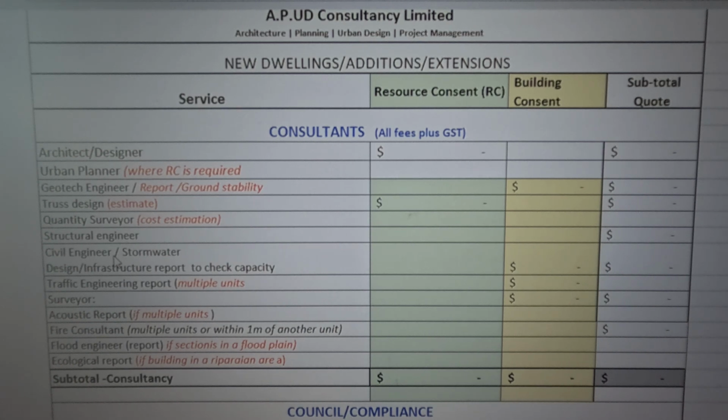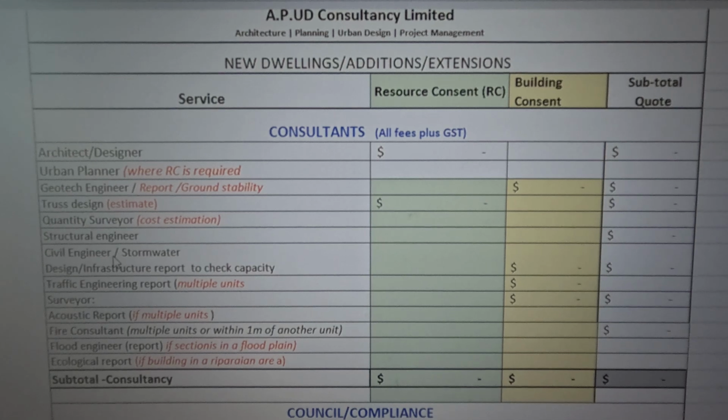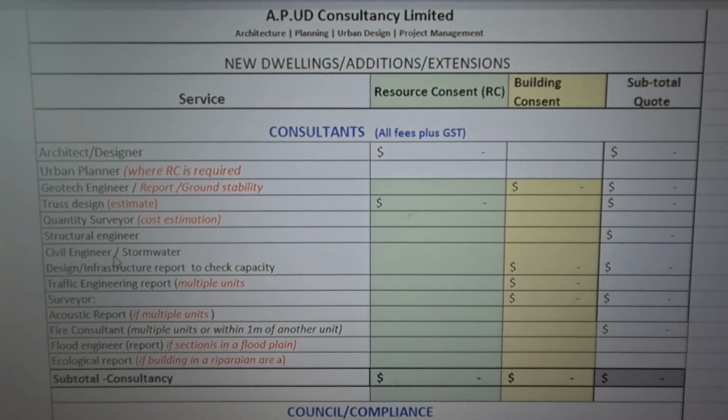Then, of course, surveyor. I've talked briefly about a surveyor. You're going to need a surveyor to give you the points, the levels. If you have a sloping site, even if you have a flat site, you'll need a surveyor to give you some points, some levels of building. If you have a sloping site, you need a surveyor to map out those points.